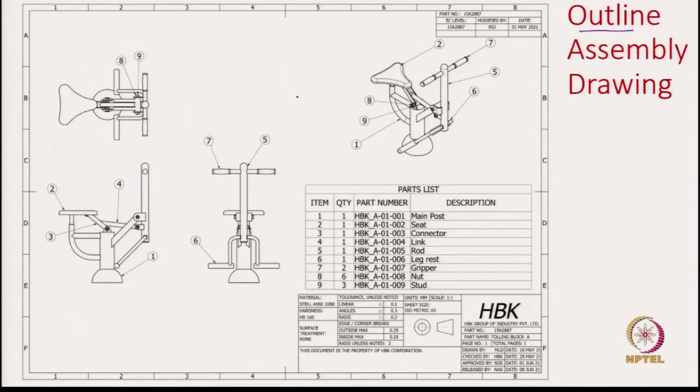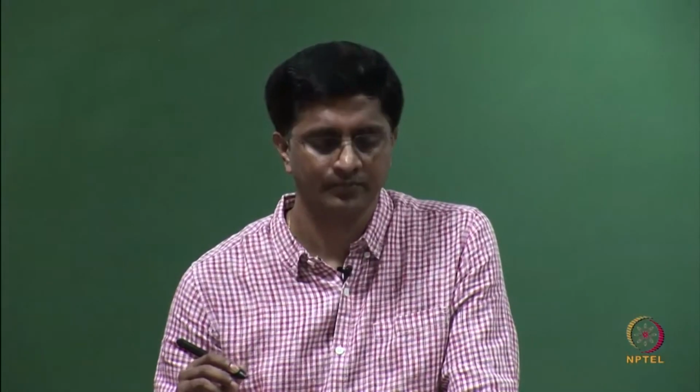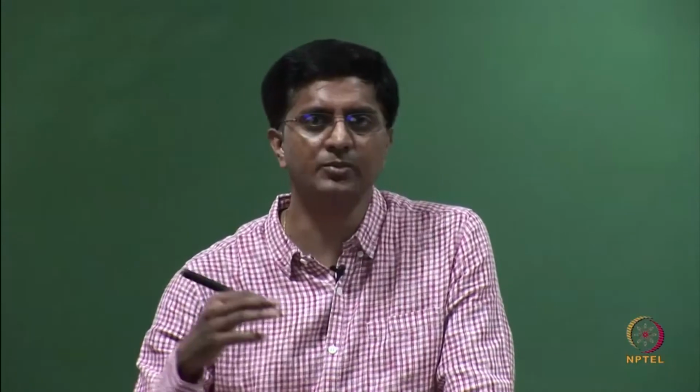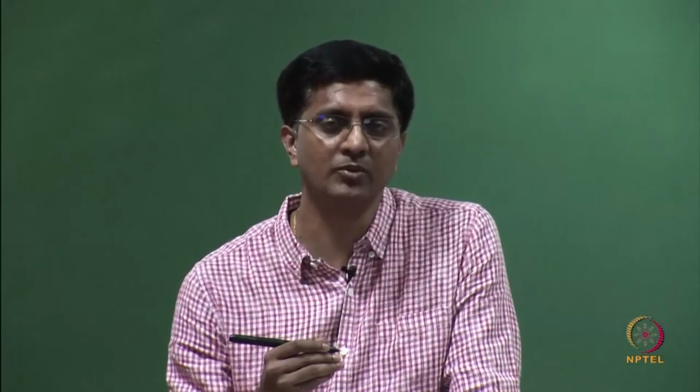There is a lot of information in this one single drawing. Of course, you can see the multi views of the assembly as well as the pictorial or isometric view of the assembly. As we have already discussed, the pictorial helps you to get a quick idea of the design, whereas the multi views help to give more precise information about each individual component.